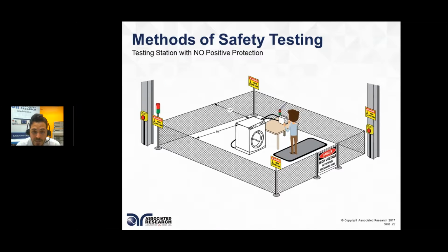We've seen some companies that build their own DUT enclosures, and these are very reputable medical device manufacturers where they'll have a huge gate that closes and controls the interlock. But something like that isn't mandatory, right? It's not necessary. You can cage off or gate off a 10-foot area where unqualified people can't enter.